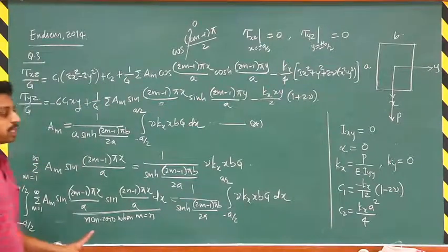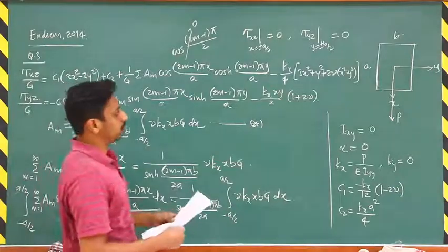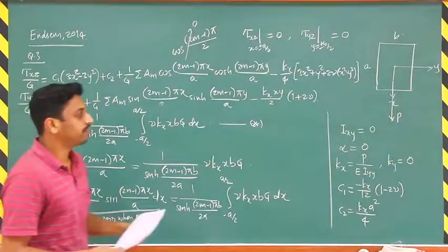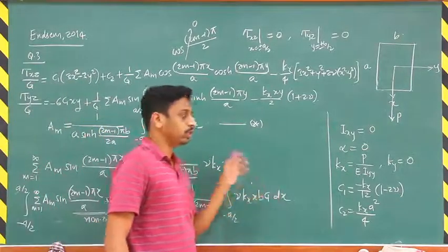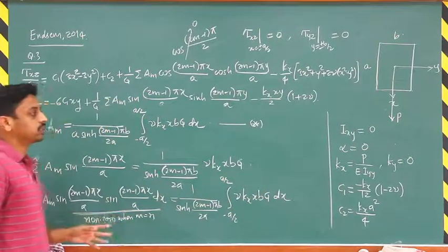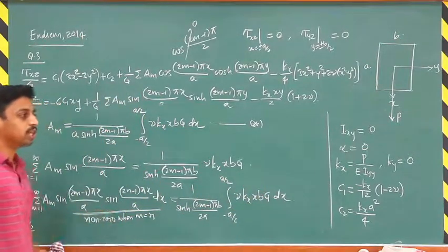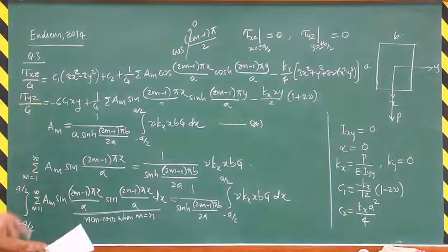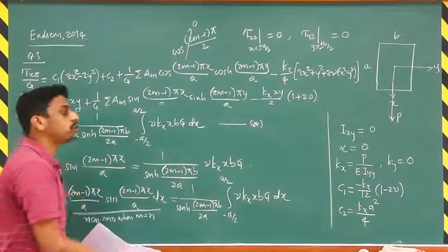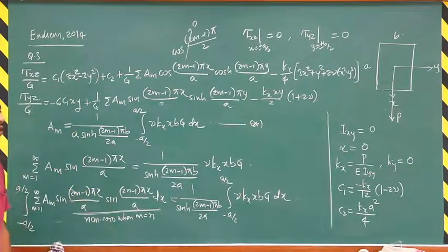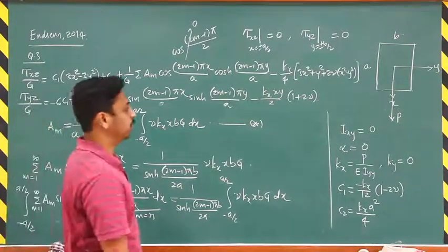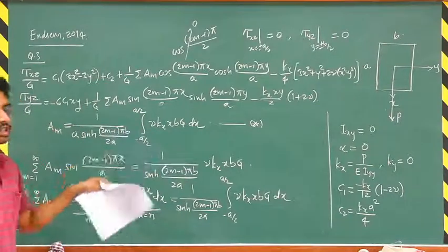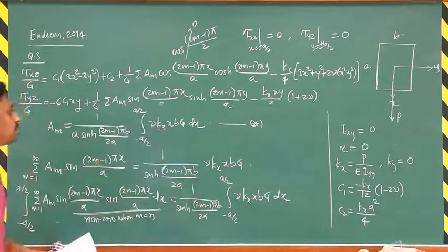So to summarize all these exercises, in most of the problems you will be given stress fields which involve certain constants. You have to find these constants by making use of appropriate boundary conditions. To check your solution, you can always put them back into your stress field and see whether your traction boundary conditions are satisfied or not. This way you can verify your solution.